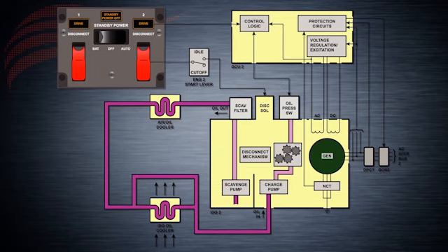As is mentioned in the 737NG engines and power plant lesson, the high-pressure shaft turns the N2 rotor, which also powers the integrated drive generator through the engine accessory gearbox. Because engine speed is variable, the gearbox speed is also variable. The IDG takes this variable input speed and converts it into a constant 24,000 RPM for the internal AC generator to produce power. The objective of this is to provide a uniform electric supply during all phases of flight, rather than having the cabin lights dim down when engine power is reduced to commence a descent.